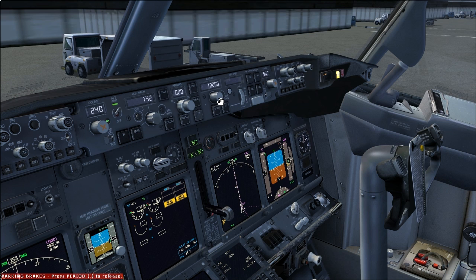And then for here, our altitude, we're just going to put our cruise altitude. We normally put the first altitude ATC clears you to, but since we are not using ATC, we can just put our cruise altitude and let the VNAV bring us right out there without having to keep resetting the MCP. And the VNAV, on VNAV. And if LNAV is on, yes it will.